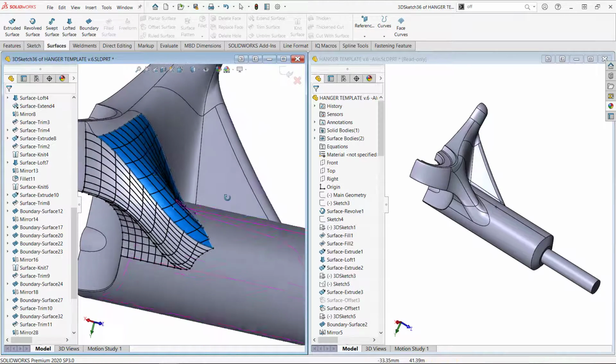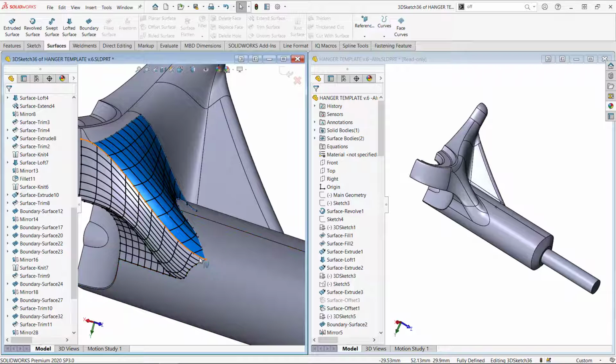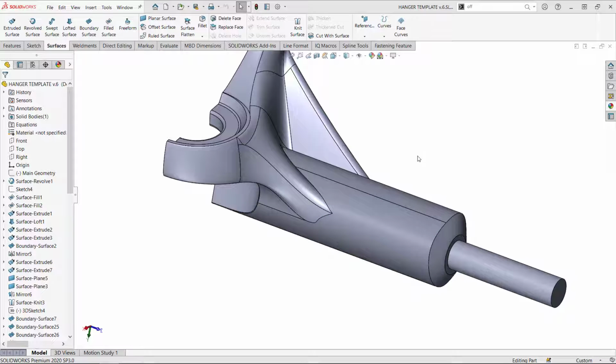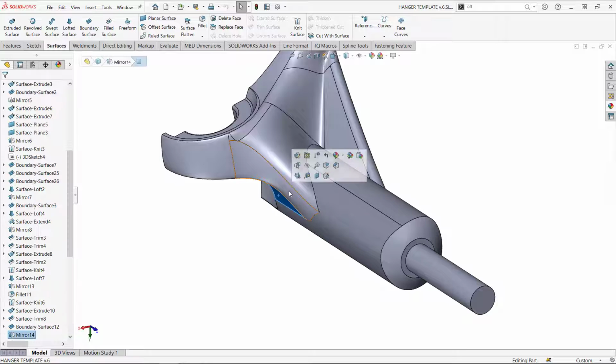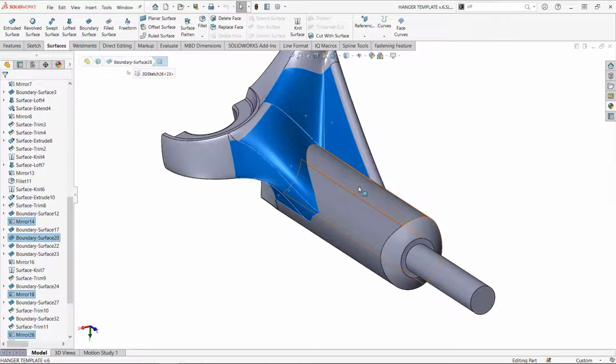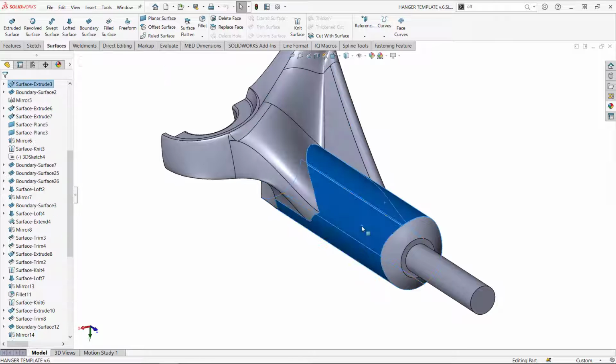Now, even if you try to use other techniques, the biggest problem would be to create the original edges from which you're going to start the blend on both surfaces. So let's try to achieve just that. This is the purpose of this video. If you find it interesting, please keep watching. As I mentioned, the goal is to create the edges from which we're going to start the blend. So let's trim these faces by an offset of these two faces with about 2mm.